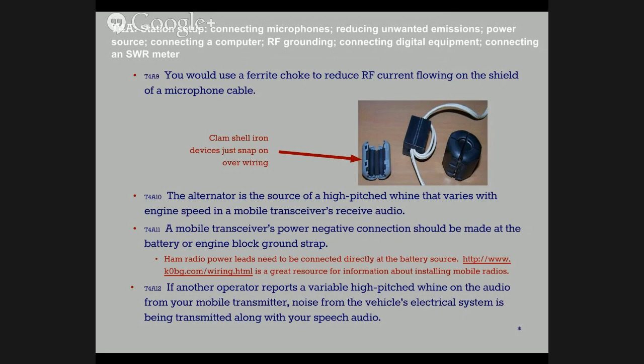In mobile installations, sometimes you'll hear alternator whine, a high-pitched whine in the transmit audio or in the receive audio, which comes from the alternator. The alternator generates an AC current, which gets rectified. But a lot of that can seep into circuitry. Sometimes also engine control units.